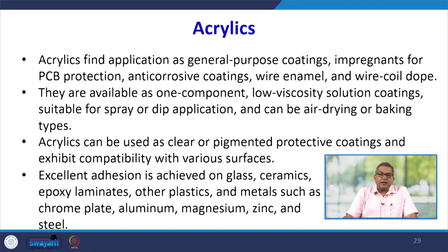Let's talk about acrylics. Acrylics find application as general purpose coatings, impregnants for PCB protection, anti-corrosive coatings, wire enamels, and wire coil dope. They are available as one component, low viscosity solution coatings suitable for spray or dip application, and can be air dried or baked.